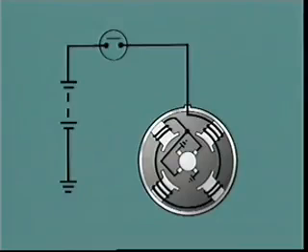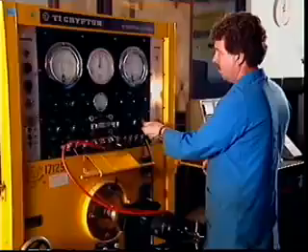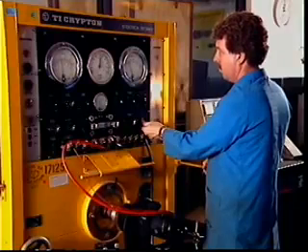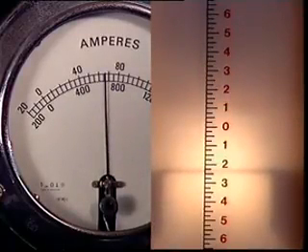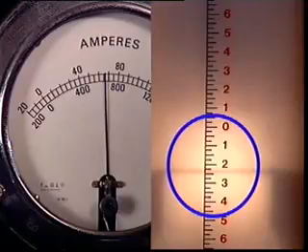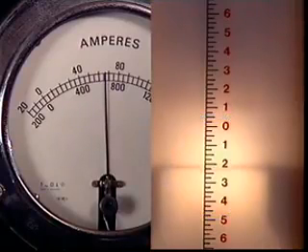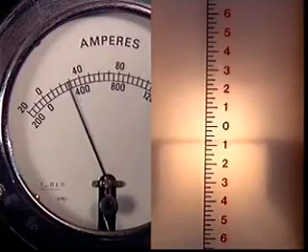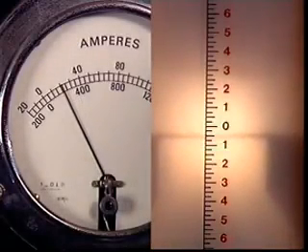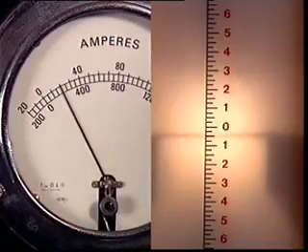Starter motors with electromagnetic field windings for light vehicle applications are series wound motors. Because the resistance of the field and armature windings is low, the current flow is high when the motor starts under load, and this generates a strong magnetic field that will produce a high turning effort at low speeds. This high initial torque drops sharply as motor speed increases due to the back EMF induced in the armature windings, which opposes current flow and reduces torque output.